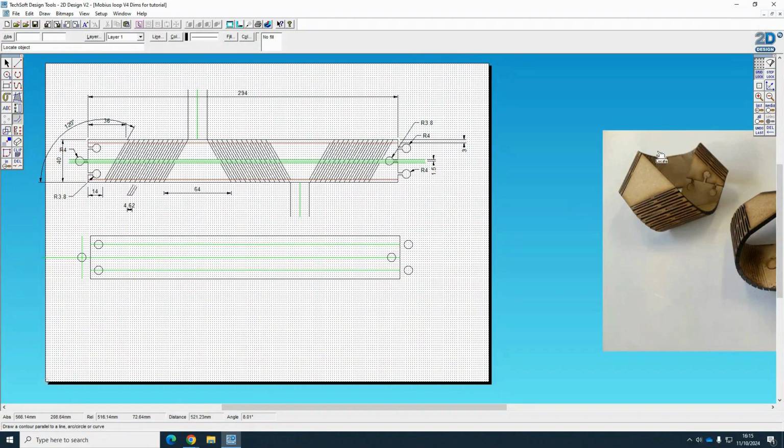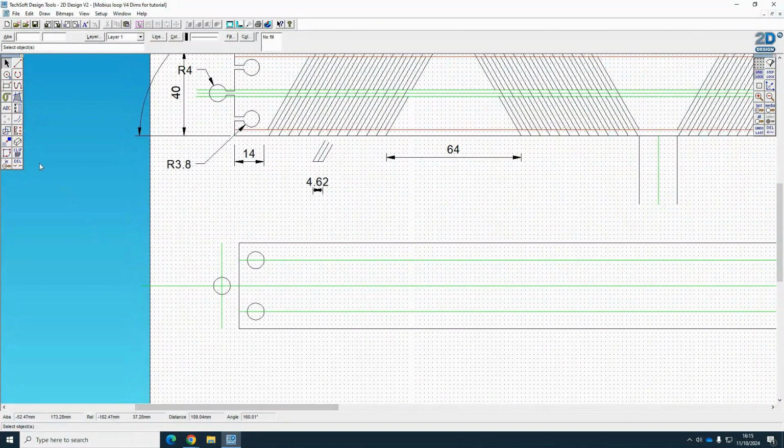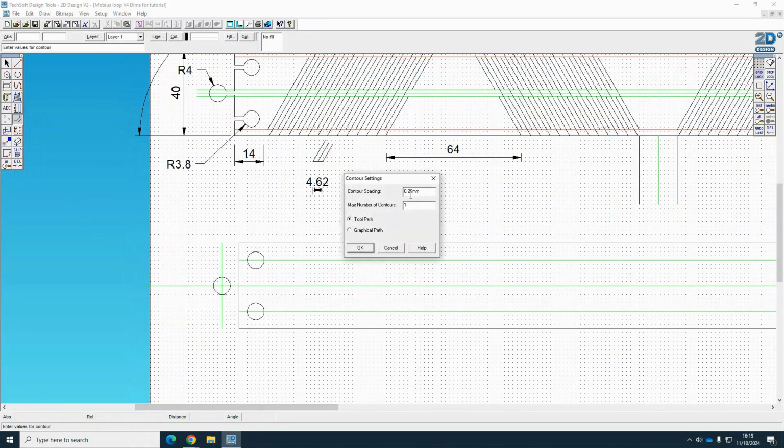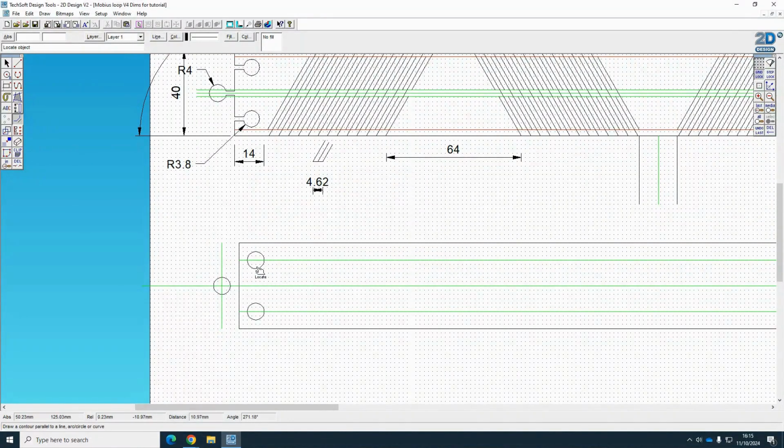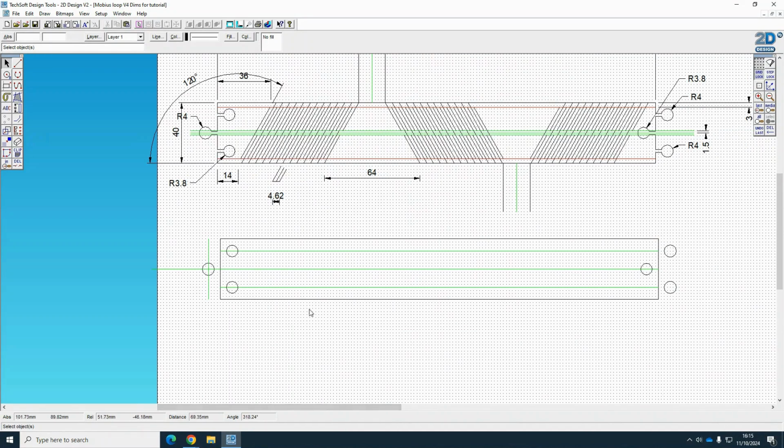And I'm going to set that circle now. And that's the inside one. So I can then delete the outside one. I'll do that now because sometimes I'll get confused. And I'll do the same on this side. So 0.2 millimeters, but on the inside of these two. Delete, delete. And there we are. We'll have a nice tight fit on the sockets here.